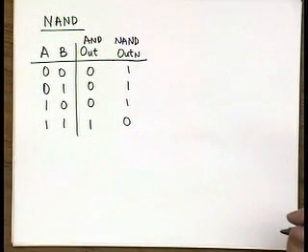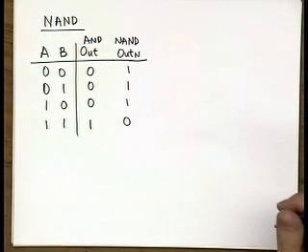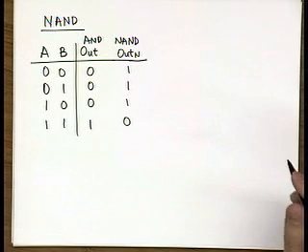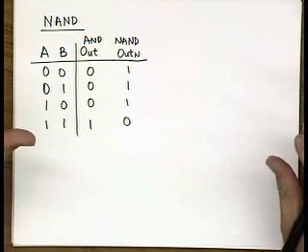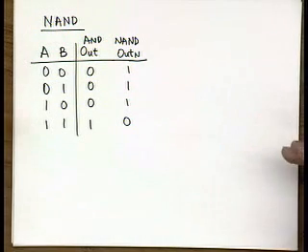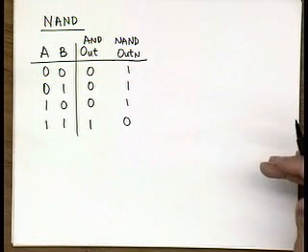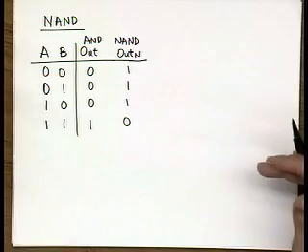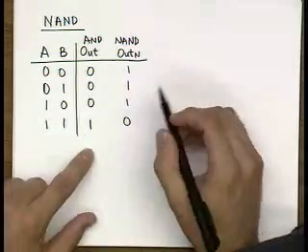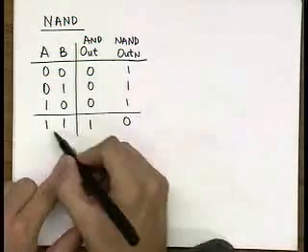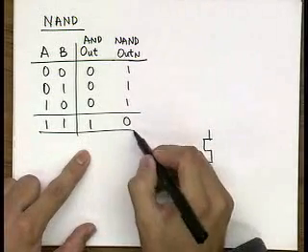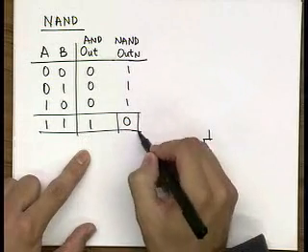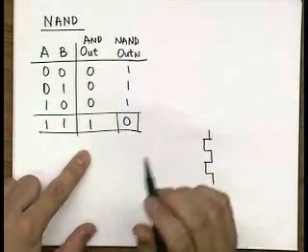So we now know that a series connection of two NMOS transistors implements the AND function. But since we are pulling down to 0, we are actually implementing a complementary function with that pull-down network. So we're implementing a NAND. In this case, when both of these transistors are turned on, this is the pull-down. We say that the output is always implemented as 0 using the pull-down network.